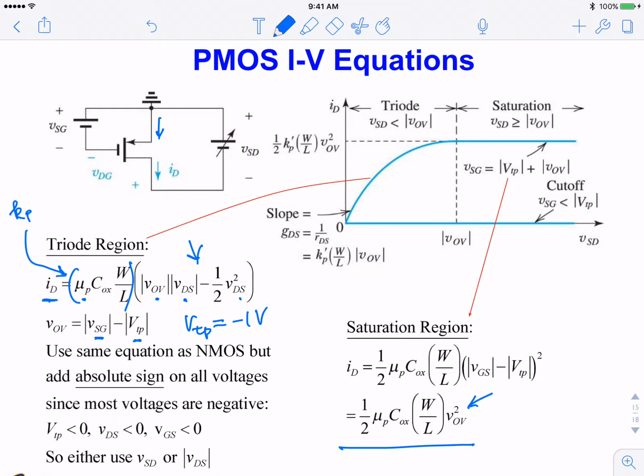And why is PMOS usually wider than NMOS in physical size? Doping concentration? Mobility? Yes. Electron mobility is 3 times higher. In order for them to have the same current, and most circuits you will see later have this generic trend of a stacked PMOS on top of NMOS, the current needs to be the same.